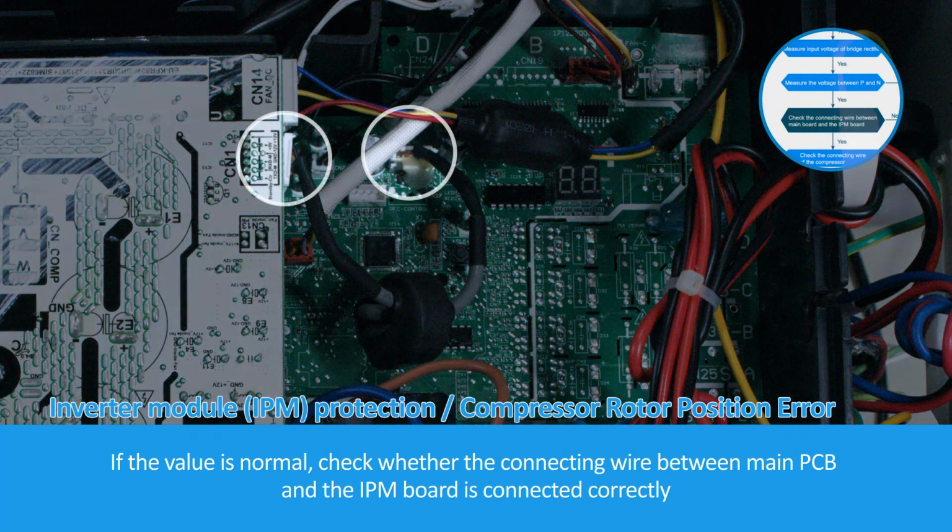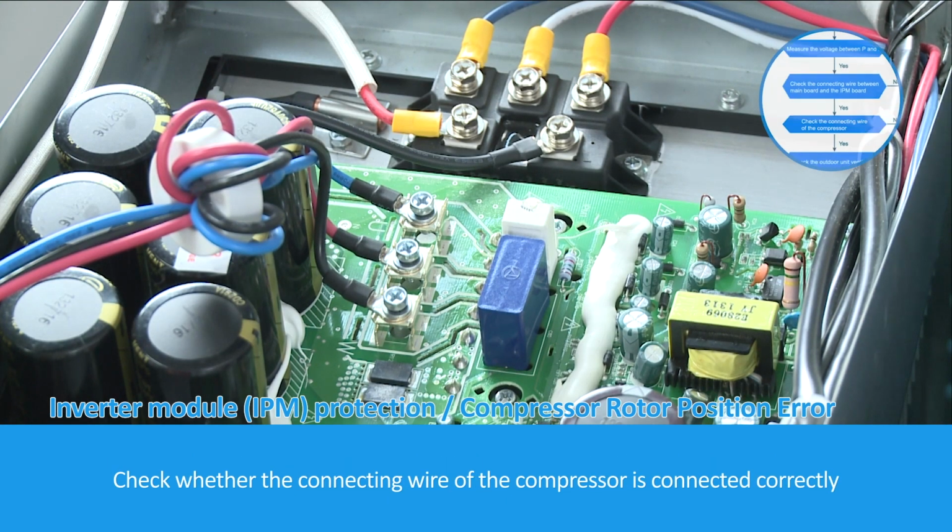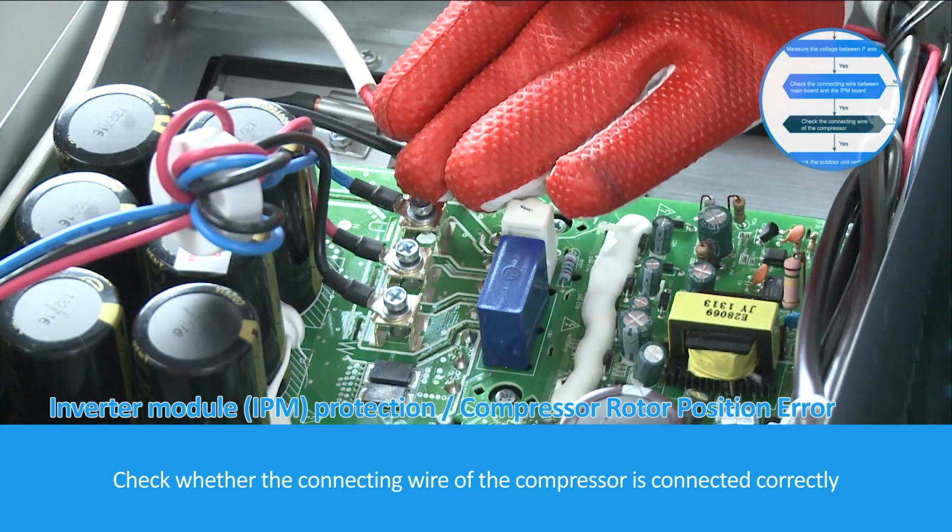If the value is normal, check whether the connecting wire between the main PCB and IPM board is connected correctly. Check whether the connecting wire of the compressor is connected correctly.